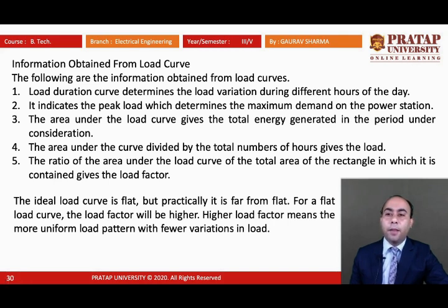The area under the load curve gives the total energy generated in the period under consideration. The area under the curve divided by the total number of hours gives the average load, and the ratio of the area under the load curve to the total area of the rectangle in which it is contained gives the load factor.